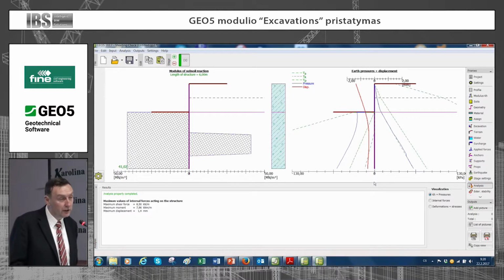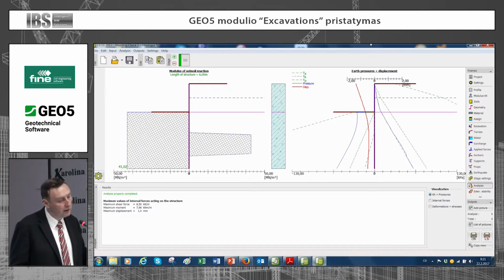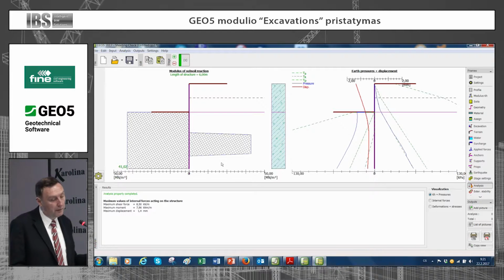And in the sheeting check, we calculate with the stiffness of soil, that is modeled by modulus of subgrade reaction, and of course with the stiffness of the construction. And the stiffness has a high influence on the result. In sheeting design, it's not important what type of structure you have, but in sheeting check, I would say all stiffness and all material properties are important for the results.